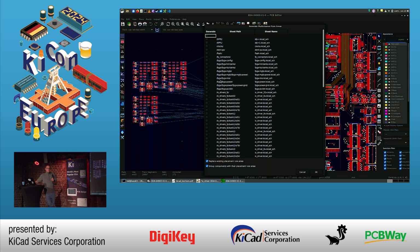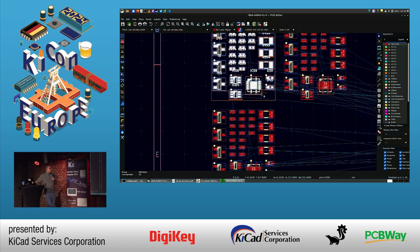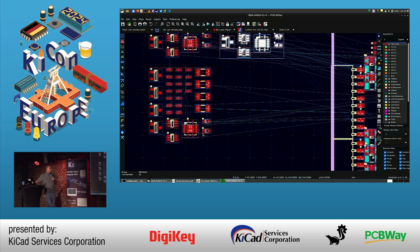A rule area is a polygon on the PCB that you can use as a keep out, or as a sort of holder for a bunch of components. You can define it either using a design rule expression or with this shortcut, generate rule areas, which will do it for you. Just choose the sheet instances in your schematics you want the rule areas made for. And there we go. So here is our rule area for channel 1, channel 2, channel 3.